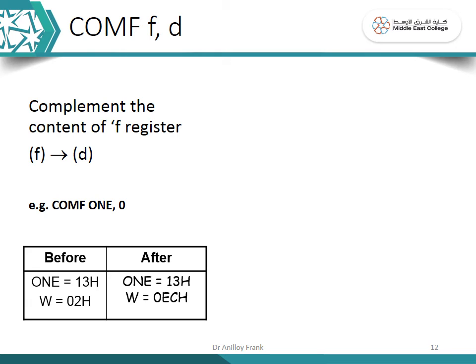The COMF instruction. The COMF instruction complements every bit. If a bit is 0, it is complemented to 1. If the bit is 1, it is complemented to 0. It does not affect any flag.